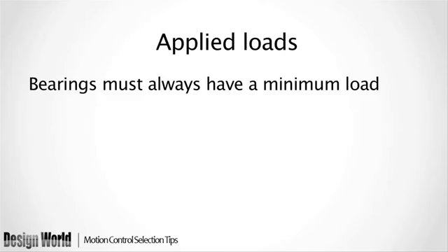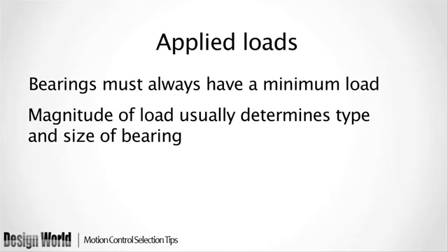Bearings must always be subjected to at least a given minimum load to provide for proper rolling element rotation and enhanced lubricant film formation in rolling contact areas. The magnitude of the load is one of the factors that usually will determine the type and size of the bearing for any given application.